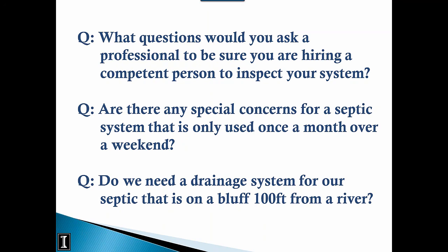Most of the codes up here wouldn't allow it within 50 feet of the river. One of the major concerns being a river is flooding, of course. You don't want your leach field to be in an area that's going to flood over, so that is a major concern. Also, the depth of groundwater. Anytime you're near a waterway or wetland, you might not have the groundwater depth that's required where you are. You want a minimum of 2 feet nationally, but the more the better, to get down to the highest groundwater tables. So you also have the setbacks.